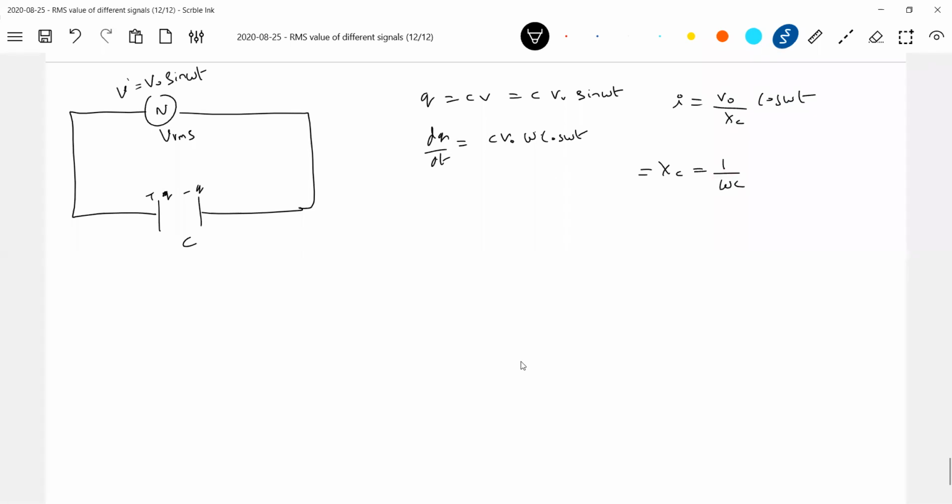This is called capacitive reactance. All of you, this is very important, because for everything else I'll apply Ohm's law, KVL, KCL, but this is very important. I call it capacitive reactance, a word you say: reactance, not resistance. It depends on the capacitance and angular frequency. So finally this equation ends up as I equal to I naught cos omega t.